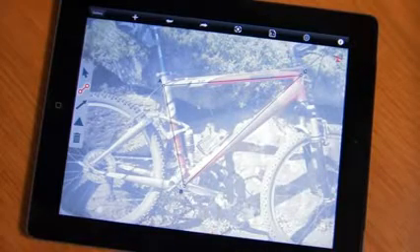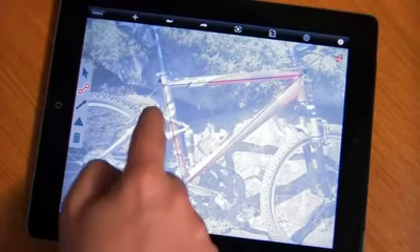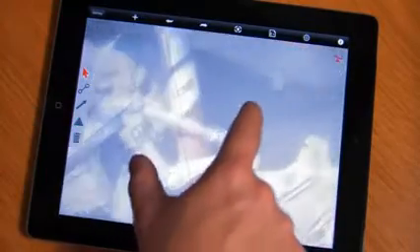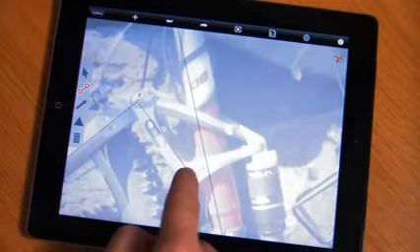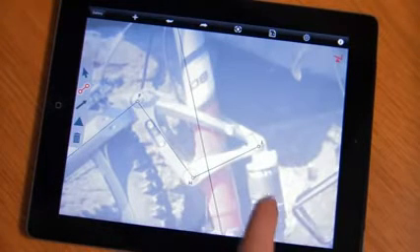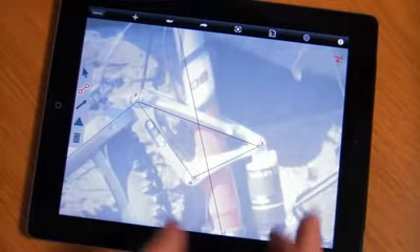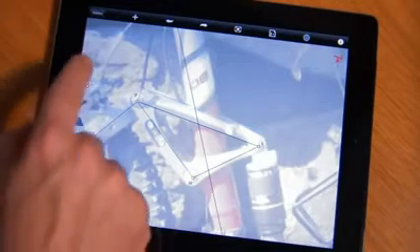So here we're adding the elements for the frame. Next we'll add the simple lines of force for the back of the frame. And then we'll zoom in here so that we can add the force elements for this rocker arm. And notice that we've got a piston here at the back, which the engineer wants to minimize the reaction force across such that he can use a smaller piston and reduce the weight of the overall bike.